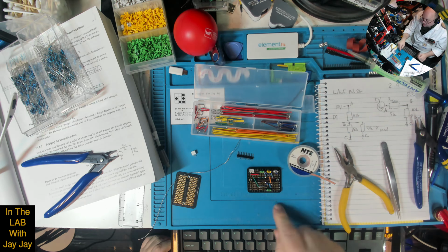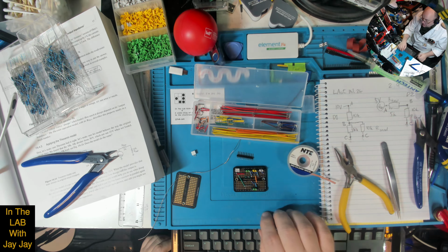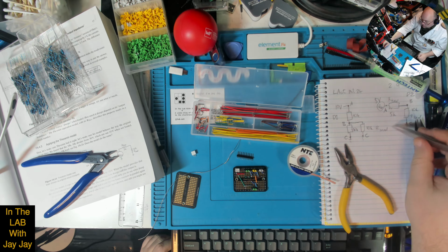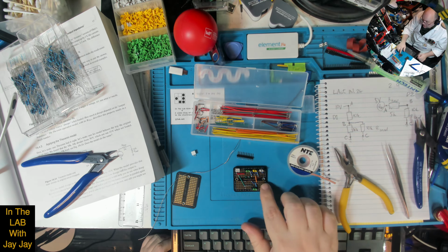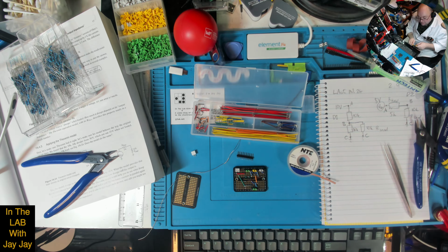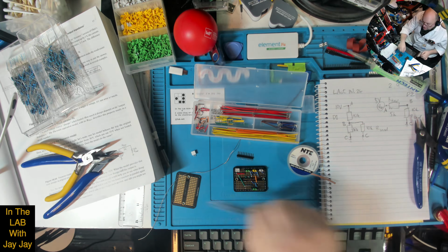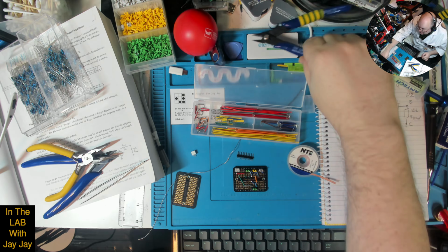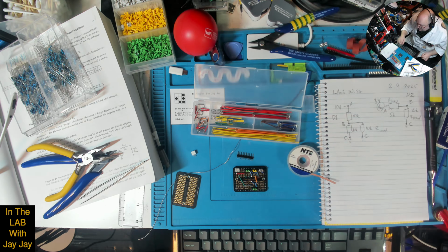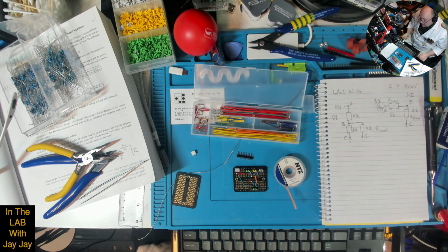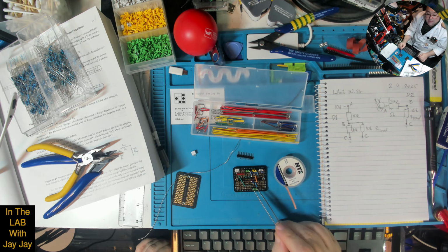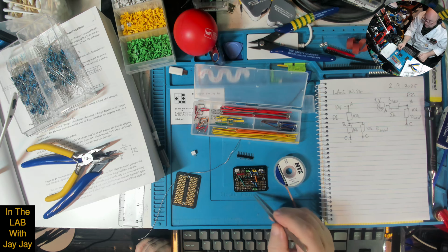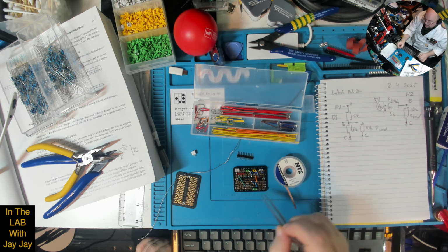It's the actual circuit as opposed to the Thevenin model, which we'll also be building. So this is the first circuit for us to test. And let's just draw up our testing system. We're basically going to run the numbers with load and with no load. So I've got this jumper down the bottom here that can optionally attach or detach the 10K load.